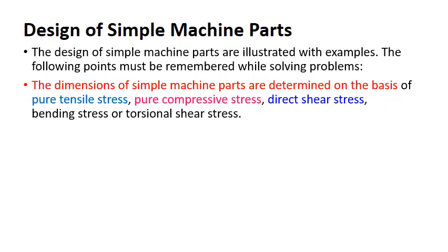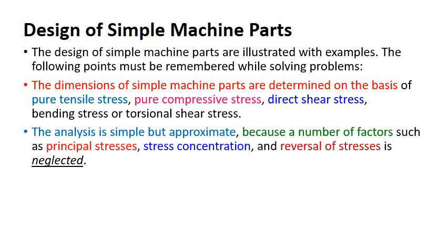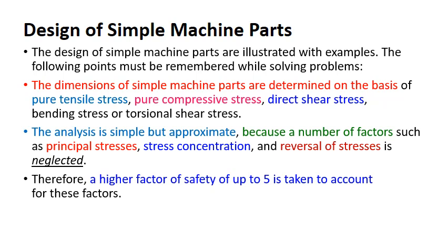Your component will also be subjected to a simple loading situation, by neglecting principal stresses, stress concentration or any fatigue loading. We will address this separately in detail in the upcoming chapters. And of course, we also employ a factor of safety. We may not exceed beyond 5.